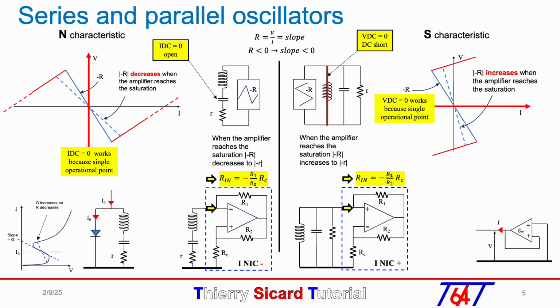If we look at the output current I equal to GMV, we will notice that the current is flowing out of the amplifier, which means that the output impedance of the amplifier seen from the outside is negative. The I versus V characteristic shows a current saturation, which allows for an increasing conductance upon saturation.